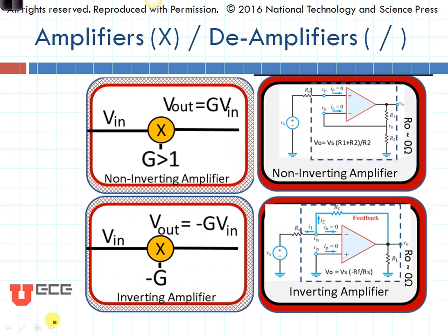So here are two other system and circuit design cards. Here's the system side, here's the circuit side. There's the non-inverting amplifier that you're used to. Here's an inverting amplifier where we multiply by a negative number. While we're at it, let's also take a look at the very important input resistances for these circuits. When I look into this circuit, I'm going to run up against the input resistance of the op-amp, which we know is very high. So Rin for a non-inverting amplifier is approximately equal to infinity.